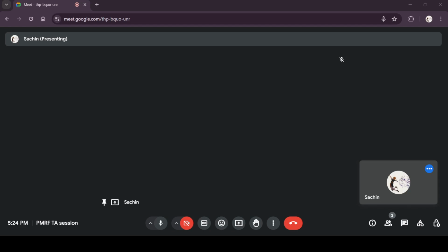Y1 is not connected to any of the minterms. There's no diode here, so Y1 is always 0. Y2 is connected to M6 and M2, minterms 2 and 6.